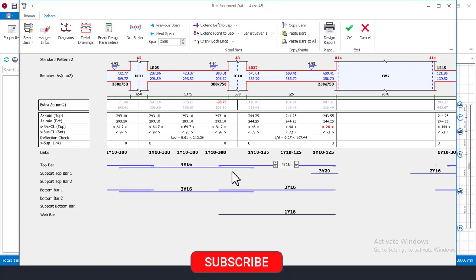So I have to add my board support layer here. Else, I can choose to use 3Y20, decrease this. You can see that, and then decrease this also Y20 and decrease. But I want to try Y16 first for my beams. So I'll come here right now, increase to 4 Y16, decrease this, and then decrease this first, and then decrease this. Okay, I want to avoid using large diameter of bar for my beams, just to save the client's money.